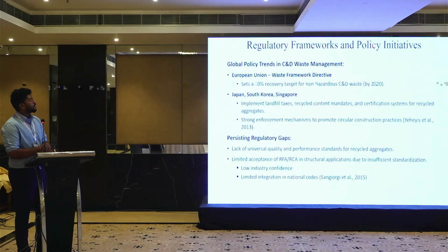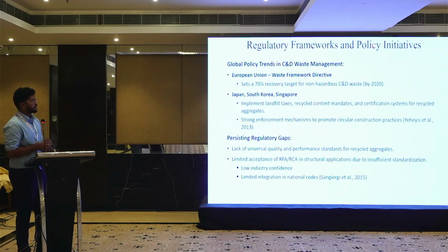Regulatory frameworks and policy initiatives. In Europe, we have studied that Europe sets a 70% recovery target by 2020, with content mandates and a certificate system for recycled aggregates. Persisting regulatory gaps mean a lack of universal quality and performance standards for recycled aggregates, and low industry confidence, limiting integration in national codes.